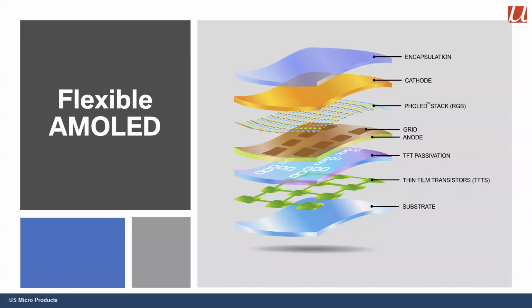What we need in the case of a flexible AMOLED is all those same layers as we have in the standard AMOLED. You've got the protective encapsulation, the cathode, the OLED stack itself that moves the electrons and emits the photons. You've got the grid that separates the pixels, the anode, and the TFT that forms the memory, and all of that on a substrate that's flexible. And so you've got to design all of these layers to be flexible, and that's not an easy thing to do.